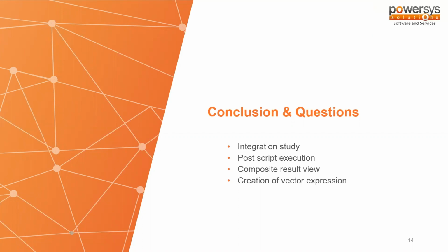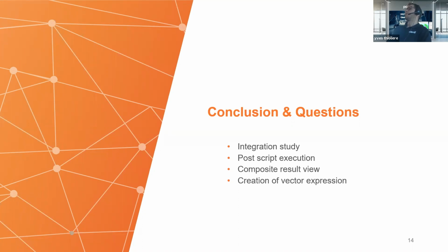Okay, I think we have a new question: how can we take into account the PWM current in the efficiency map? Yes, with the accuracy priority type. You can also check the JMAG website, where there is a step-by-step tutorial example. You start with the speed priority and then accuracy priority, and it means you can completely customize the circuit.